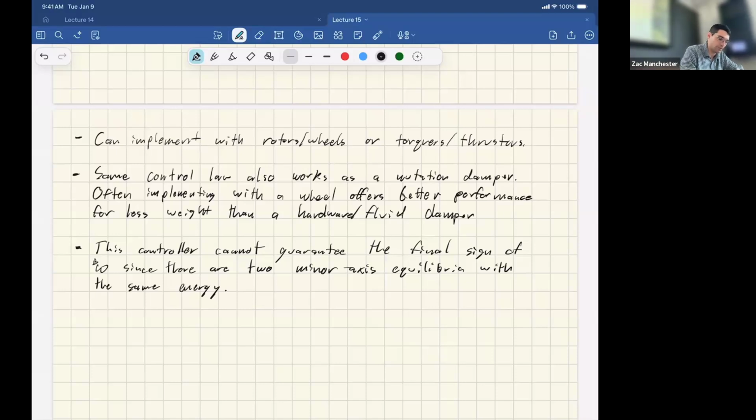So the first one, which is frankly the dumbest, is the so-called JPL configuration. This one maintains the first 3 in the classic 90-degree orthogonal arrangement, and then adds the fourth one, splitting the difference between those. This gives you single fault tolerance, but in terms of control capability envelope in the nominal case where all of them work, it's kind of the worst, or doesn't necessarily do the best.